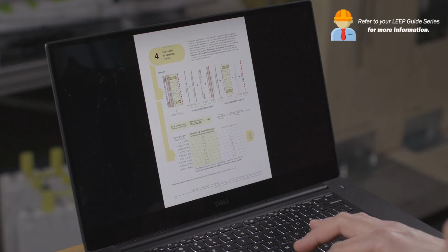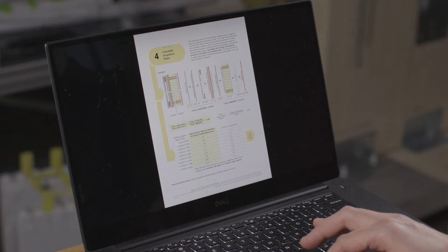Or moreover, there are a couple of different ways to look at this. The question is, how much foam or impermeable insulation do I need to put on so I don't need a vapor barrier? Likewise with vapor permeable insulation, if I've got 6 inches of vapor permeable insulation, do I need a vapor barrier? So there are 2 ways of looking at this. Generally, the higher the insulation ratio, the less vapor control you need on the inside. The whole point of doing this calculation is to figure out where you're at. There's a minimum requirement, but there's also what you might call a building science requirement.